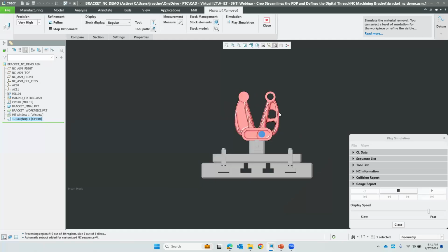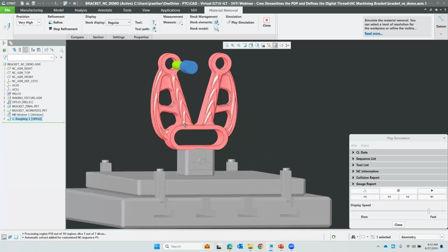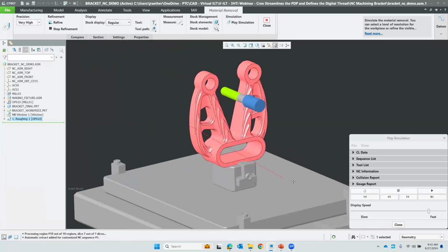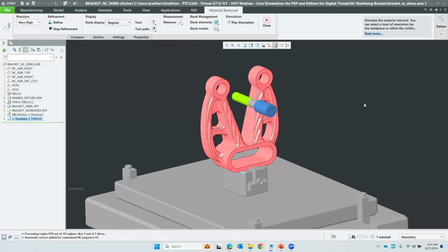Right, let's look at it from this side. All right, so the nice thing about that mill window, again, all it does is find the part. I can make crazy changes to the part, but because I didn't pick any specific entity, that toolpath is always going to update, very robust, because it knows I've got my work piece and it just finds the part. So there's the first one. We can define more. It really doesn't matter, right? I do multiple roughing, then I do my refinement and do some other things.